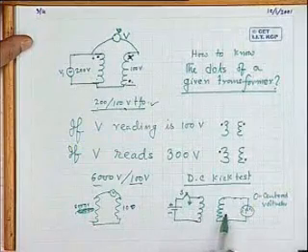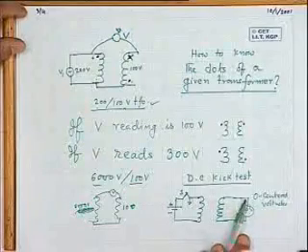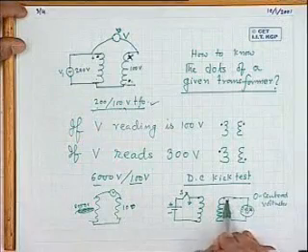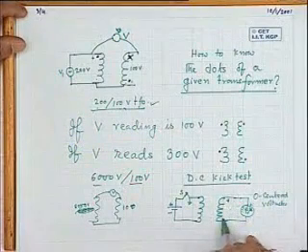You close the switch. The moment you close it, there will be induced voltage. Although it is DC, there was no flux before, and now flux will be established. There will be some d phi by dt. Of course, there will be a voltage pulse generated on the secondary side. What will be the polarity of this voltage? Suppose this voltmeter gives a positive reading, meaning that this side is plus.